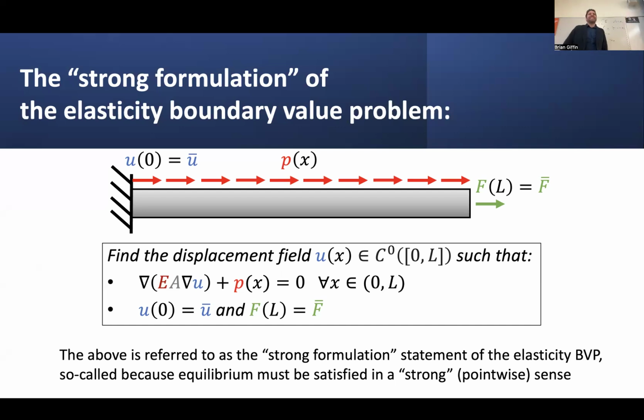And we have to find, well, you'll see where I'm going with this. Rather than a strong formulation of this particular boundary value problem, we have to find a somehow weakened formulation, or a weak formulation, of this same boundary value problem that nonetheless gives us an equivalent statement of the same problem, but which gives us a more relaxed requirement on how the internal force varies internal to this member and makes it more amenable to solving these boundary value problems in an approximate sense using methods that we'll discuss in later lectures.